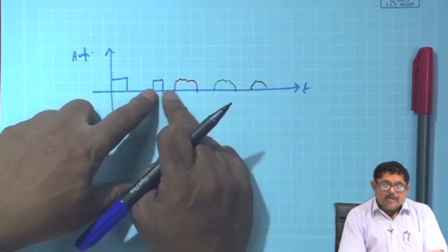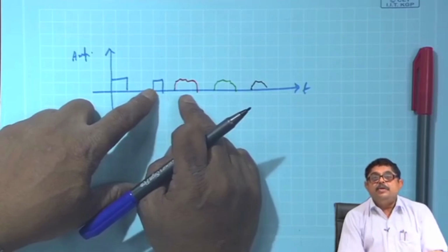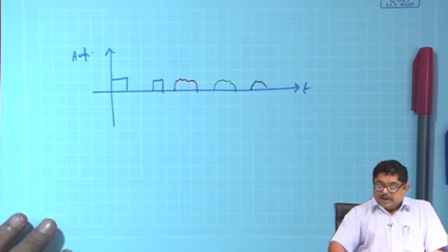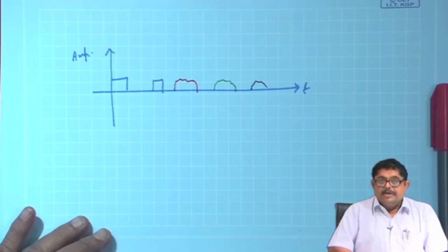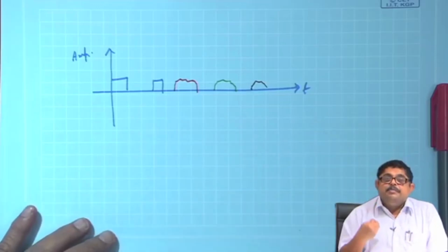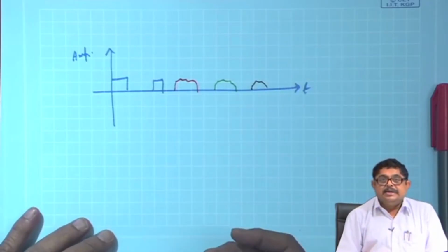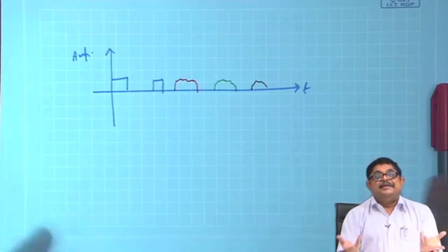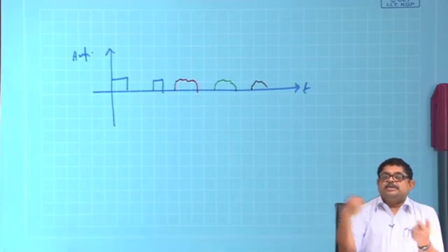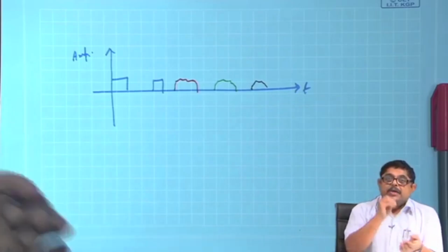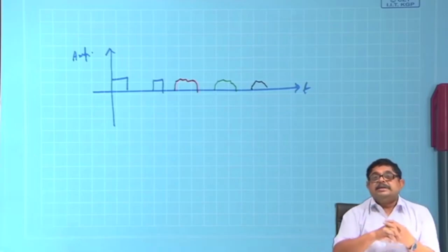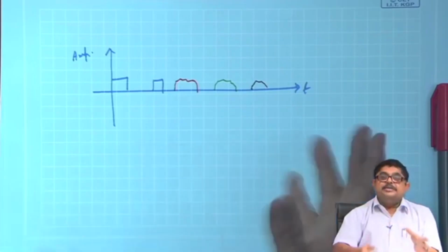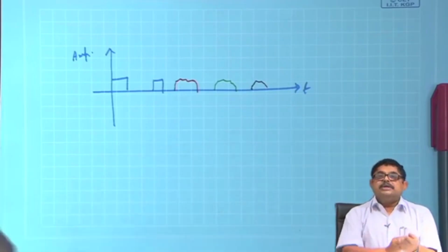So that means the measurement will be ambiguous. This is called ambiguity in the range measurement. The ambiguity is coming because I am sending repetitive pulses, and now I am losing the reference of which echo is in response to which pulse I have sent. If I could put some references in successive pulses, that could help, but that will complicate the transmitter. But we will find out that there are ways by which we can do that.